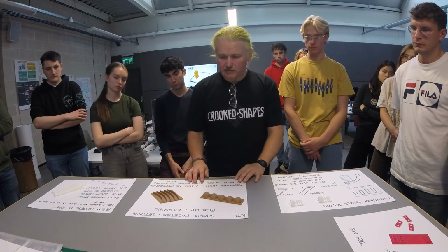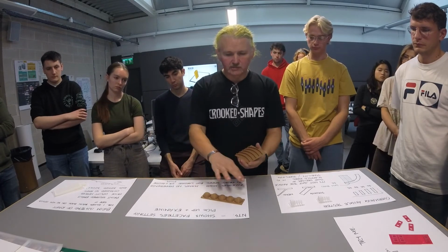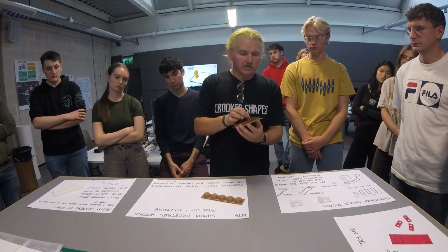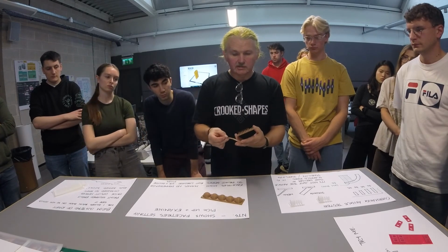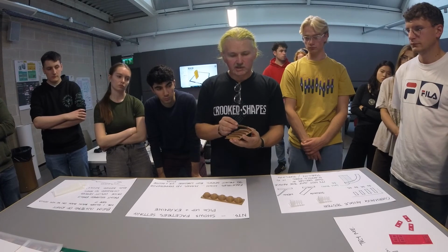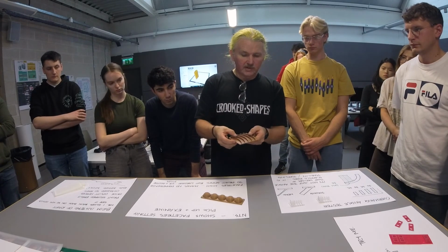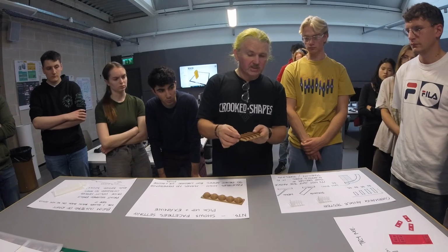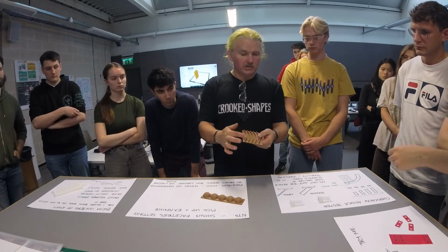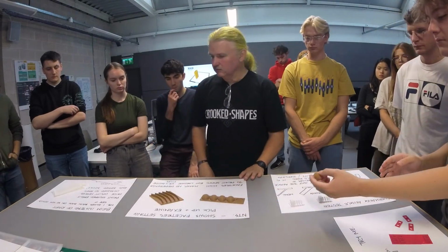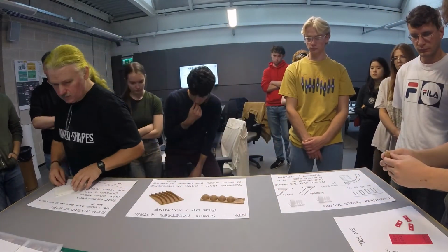So this is the same thing, facet resolution on something like a dome, and then on just a simple arc. You can really see the facets when it's on the lowest level, 0.1. But 1, 5, and 10 are pretty similar. There's not much to call between those three. So feel free to pick all these up and mess around with them.